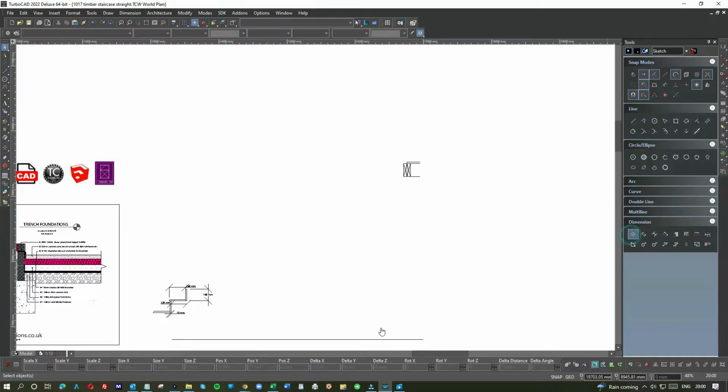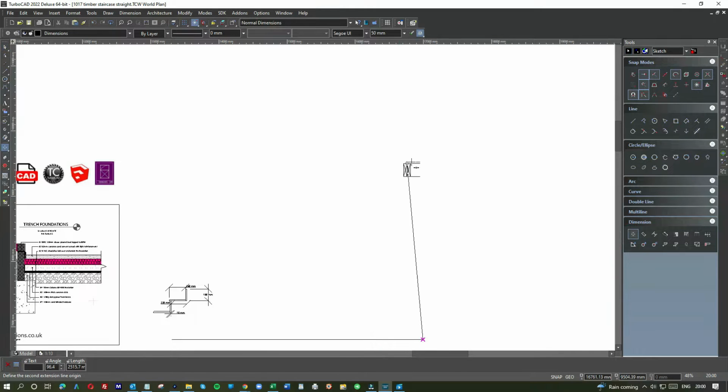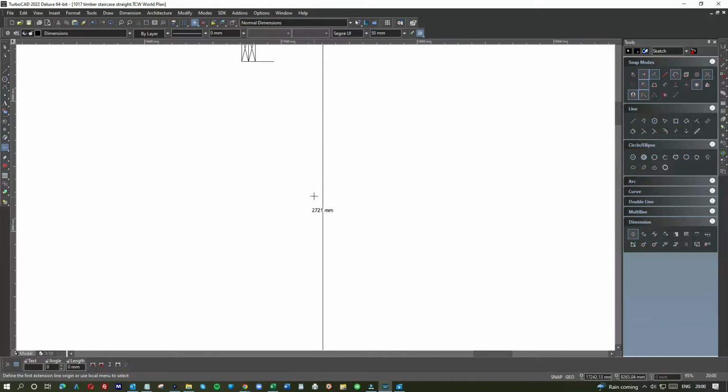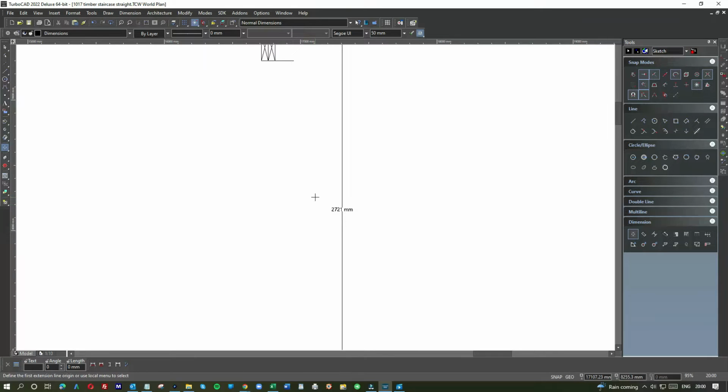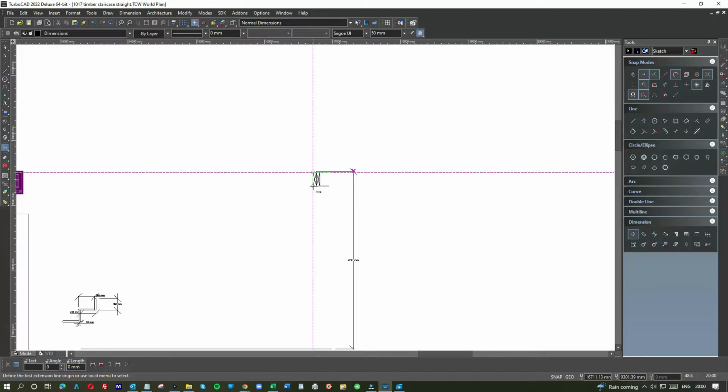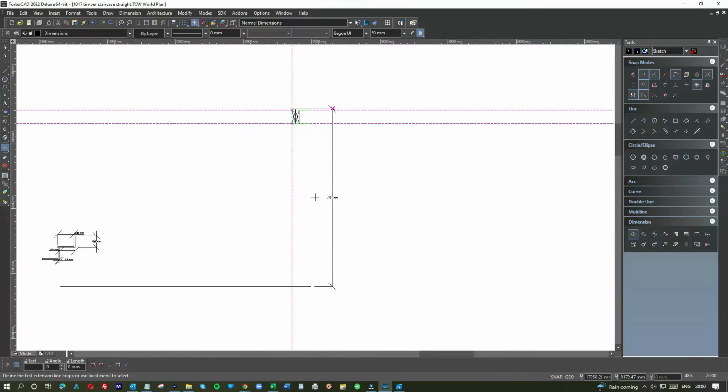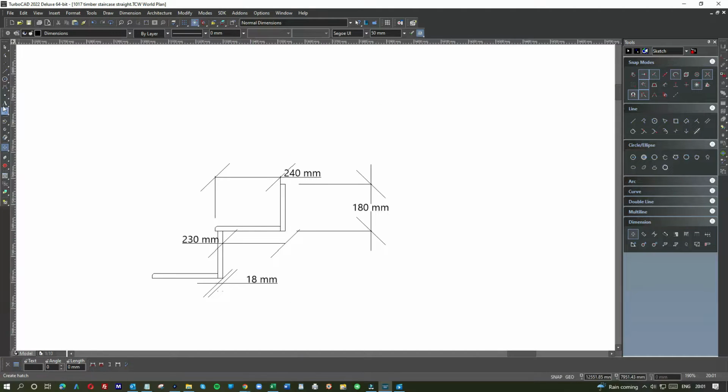So if this is say the ground floor level and we want to get to that level, then we know the height is 2721, which is a little bit tall for an average staircase. Average room say 2.4, 2.5. By the time you add the floor in, it climbs up another 200 or so, so 2721. I'm going to write that in here, 2721, so we don't forget it.